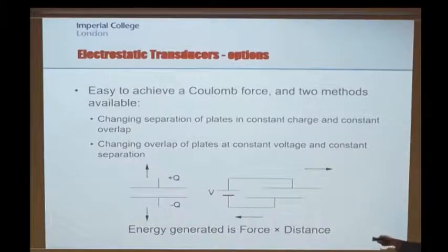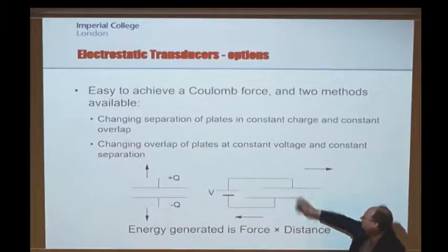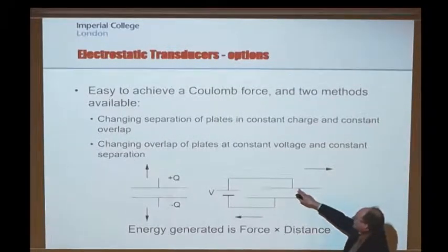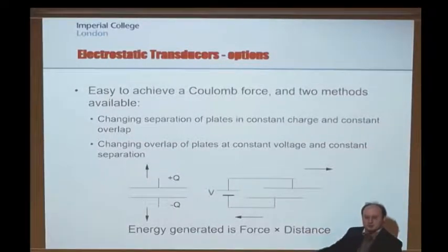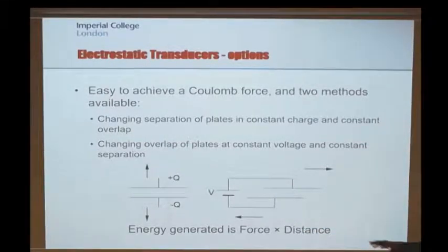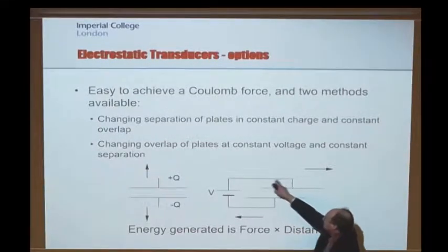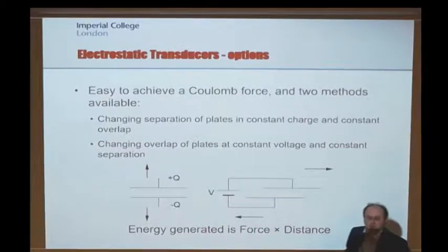So if you think about what's happening here, as I slide these plates away from each other, the capacitance between these two electrodes is continually decreasing. But if I've got a fixed voltage that I'm applying across those electrodes, then in order to satisfy my simple definition of capacitance, I've got to be dragging charge off these plates as I reduce the capacitance between them, if I'm going to keep them at the same voltage. And so that ultimately means as I start to slide these plates away from each other, charge is going to end up coming off this plate and flowing back into the power supply and therefore charging up the power supply. So that's how I'm doing a conversion between mechanical and electrical work in that particular scenario.